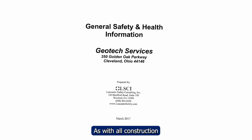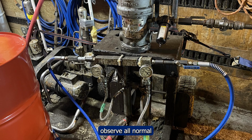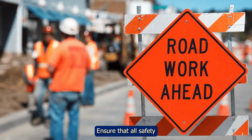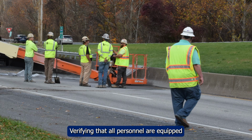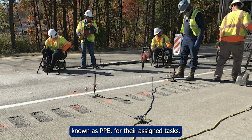As with all construction field operations, safety is a top priority. Before beginning slab stabilization work, observe all normal safety rules in the operation of pressure pumps and other related on-site equipment. Ensure that all safety protocols are in place, including the following: establishing the proper maintenance and protection of traffic in accordance with the accepted traffic control plan, and verifying that all personnel are equipped with the required personal protective equipment, known as PPE, for their assigned tasks.